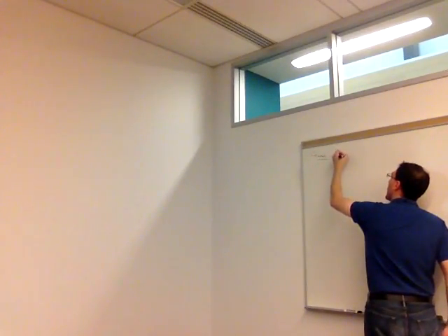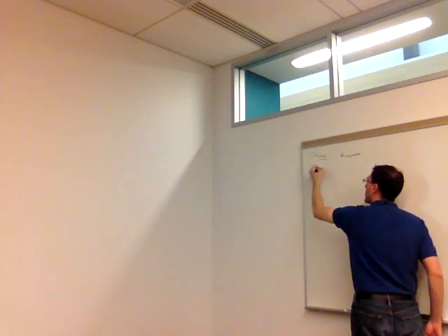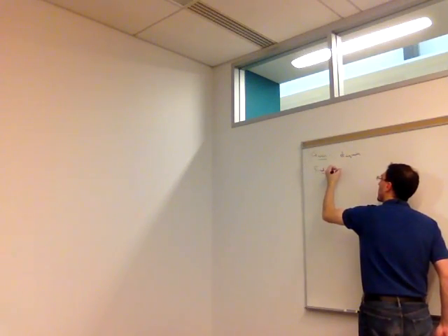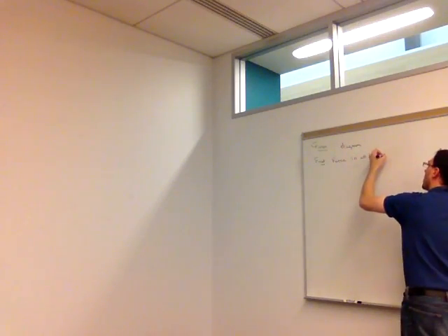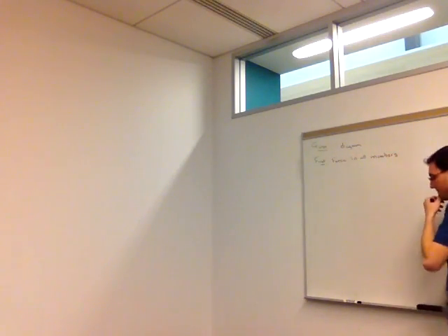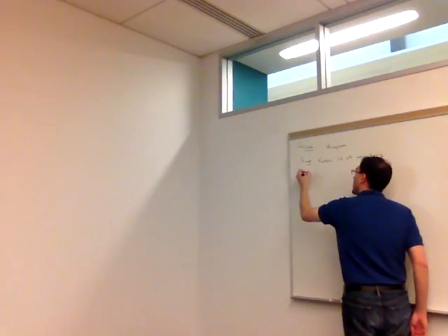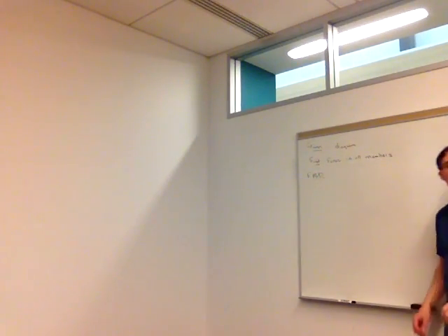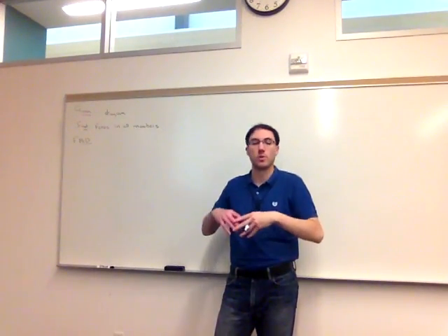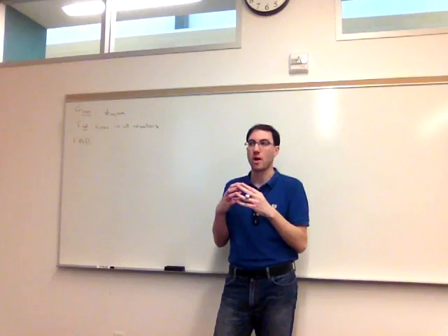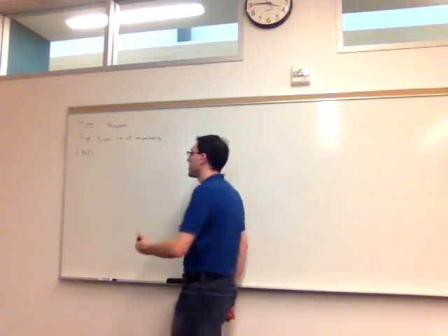So we're given the diagram, and ultimately we need to find the force in every member. So step 1, statically determinate structure. We'll draw the external free body diagram, so we'll treat it just as one bulk structure, freeing it from how it's connected, in this case, to the ground.